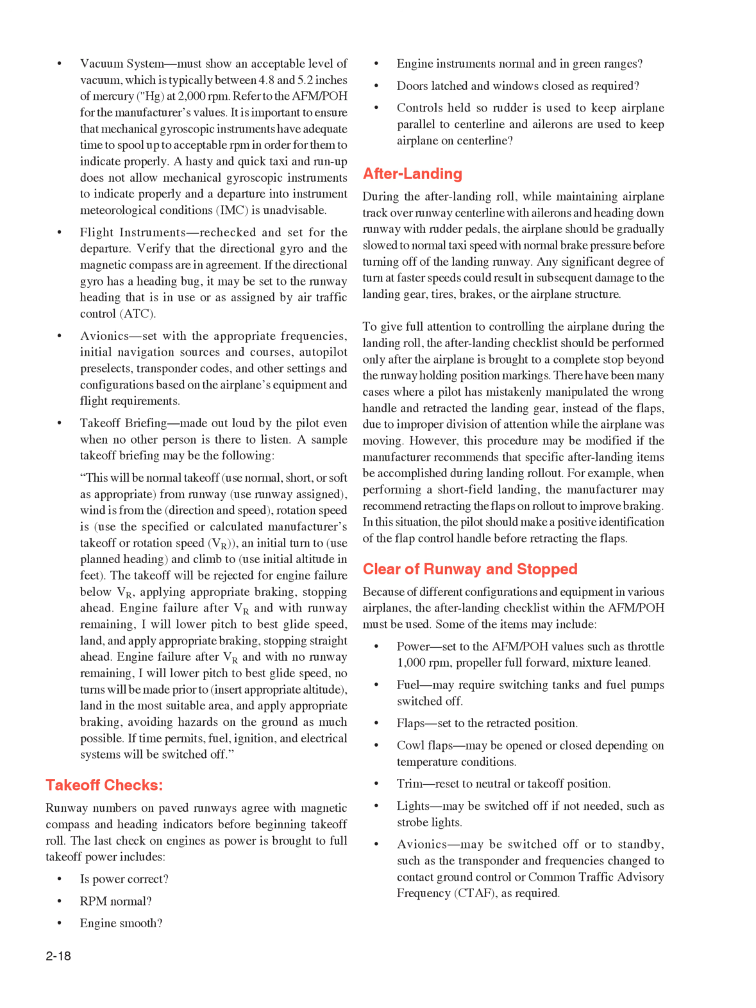Takeoff briefing, made out loud by the pilot even when no other person is there to listen. A sample takeoff briefing may be the following. This will be normal takeoff, use normal, short, or soft as appropriate, firm runway, use runway assigned, wind is from the, direction and speed, rotation speed is, use the specified or calculated manufacturer's takeoff or rotation speed, VR, an initial turn to, use planned heading, and climb to, use initial altitude in feet.